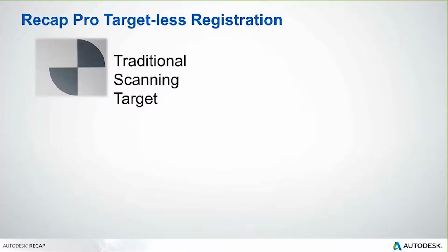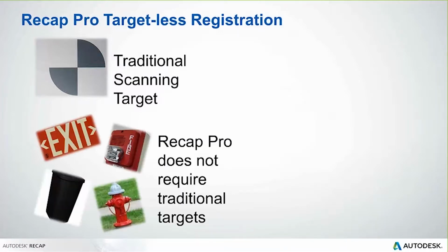And the point is that you would set those targets up, and then when it was time to bring all of your different scans together or stitch them or build a single model from those multiple scans, you would basically use these targets to align your scans. And with Recap Pro, we basically remove that process, and you can use almost anything in your scans to use for